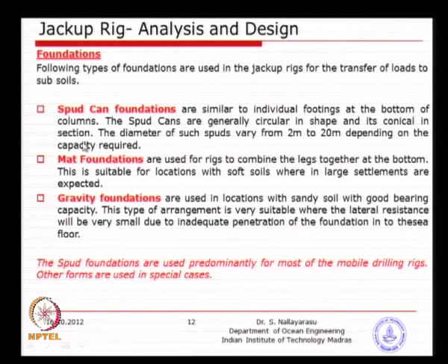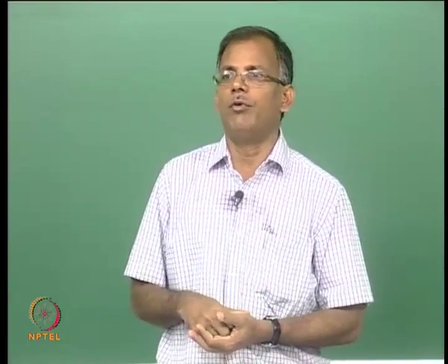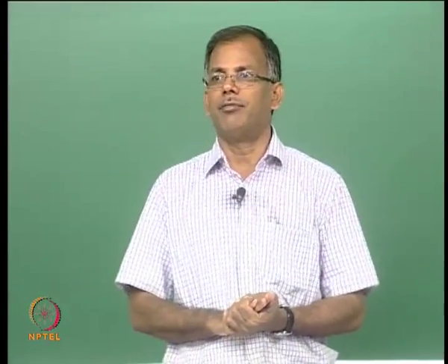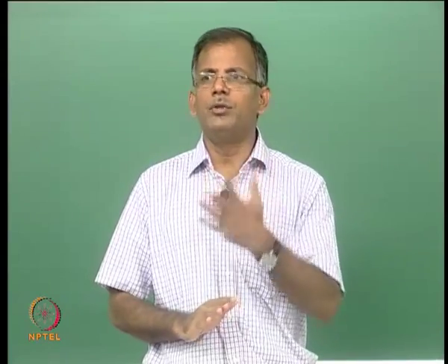Mat type of foundation is, instead of individual spread footings, if you have 3 legs or 4 legs, you combine all of them and make a larger spread. Like if you have this room with 4 columns, individual columns will have individual foundations. Instead, if you make all of them combined together like a floor, that becomes a mat foundation, which is very commonly used for multi-story buildings in clay type of soils.